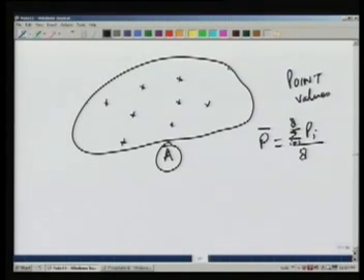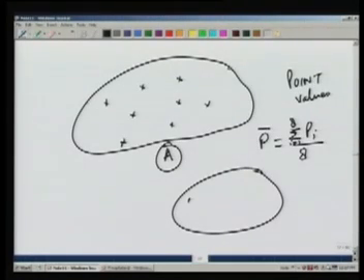The drawback with this method, although it's very simple, is that we don't give any weight to the location of the gauges in that area. So if we have an area where, let's say, 4 gauges are here and 1 gauge is here, we take the mean without considering that these 4 are very near, so they don't represent as much area, or this one is here, so how much area does it represent? It's not accounted for in the arithmetic mean method. So a modification or an improvement over this was proposed by Thiessen, and this is known as the Thiessen Polygon method.